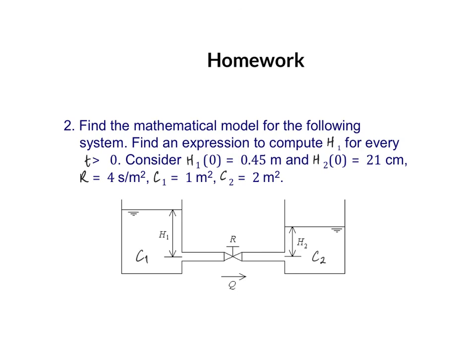In order to solve this problem, we have to apply the mass conservation principle for tank 1 and for tank 2. Also, we need to consider a flow going from tank 1 to tank 2 through the resistance. This will lead us to have a couple of first-order differential equations, which can be easily solved using Laplace transformation.